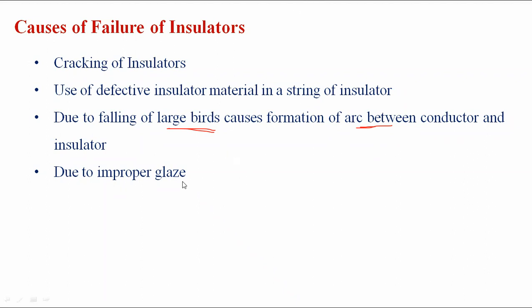Before choosing the insulator, it is considered to have a smooth surface that does not absorb water particles, moisture, alkalis and gas particles. If it absorbs them, a short circuit occurs, voltage drop also takes place and the insulator fails. And flashover occurs due to the unequal expansion of the porcelain material and due to mechanical stress. When the conductor weight is increased, stress is presented on the insulator, and at that time the insulator fails. These are the various causes of failure of insulators.